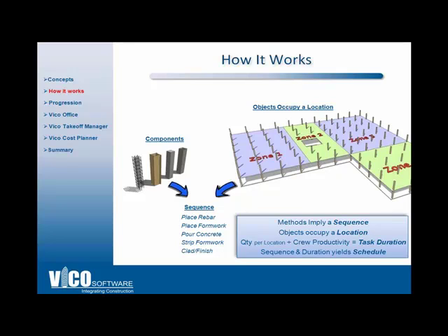give a new meaning to value engineering, because today value engineering is a negative term. It happens after design is completed. Suddenly you make the client aware of the cost, and you start stripping out the nicer parts of the design. When you have the ability to immediately give feedback to the client on design changes by combining quantities with areas, you're going to be able to perform value engineering as the design progresses, as opposed to at the very end.